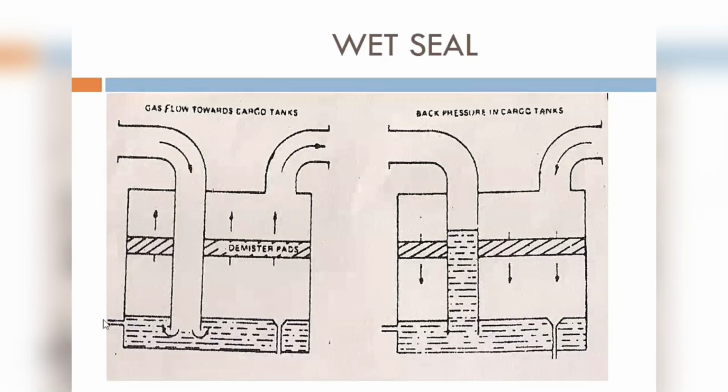Here also there is a continuous seawater supply. It's known as the deck seal water pump, deck seal seawater pump, deck seal pump basically. As we have seen in the SOLAS requirement, there are supposed to be two pumps. One pump is running and another pump should be standby. This pump is running all the time, whether the ship is at anchor, alongside, or out at sea.